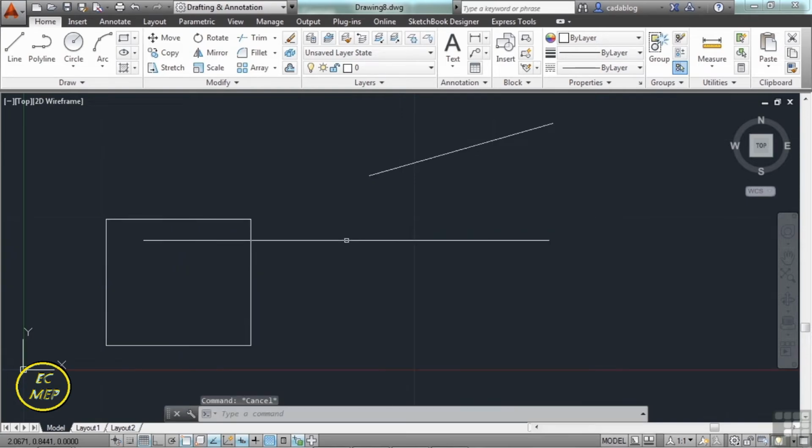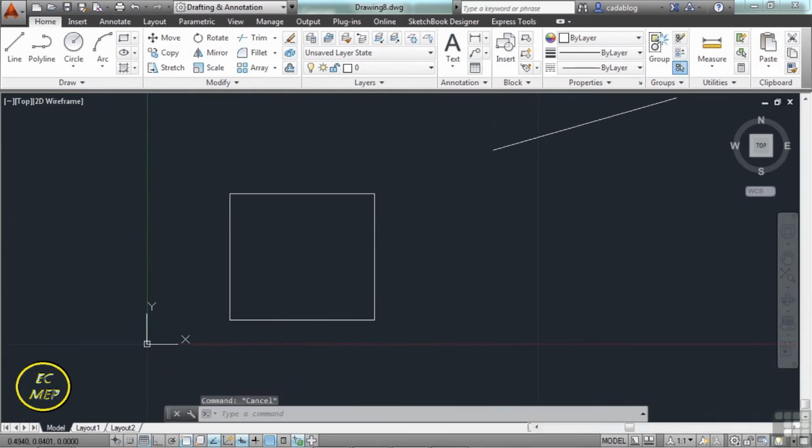As you move left or down the screen, the values of the coordinates decrease. As you move up or to the right, the values become larger. Well, every coordinate system has an origin, and it's typically found at the coordinates of 0, 0. Well, that's the same case here. We're at 0, 0. AutoCAD works the same way. So that also means that you can have negative coordinates in AutoCAD. And in math, the positive and negative values often indicate direction. So a positive direction in a line or in a coordinate means it's moving to the right or up. Negative is going left or down. It's the same sort of thing.